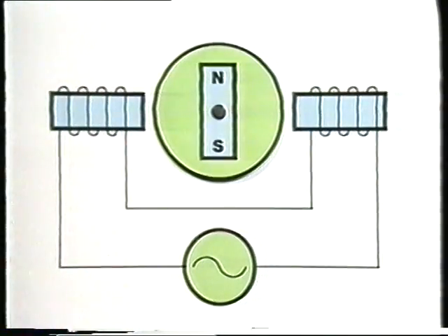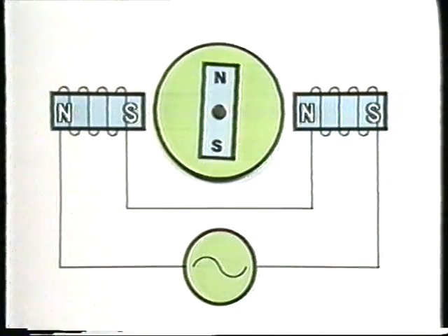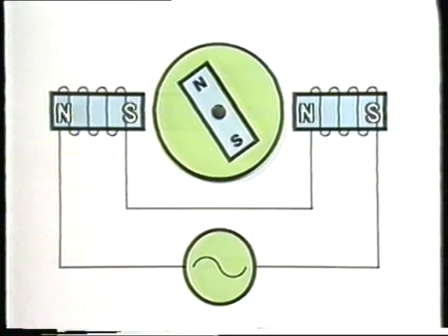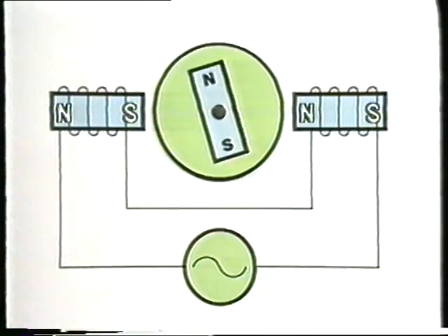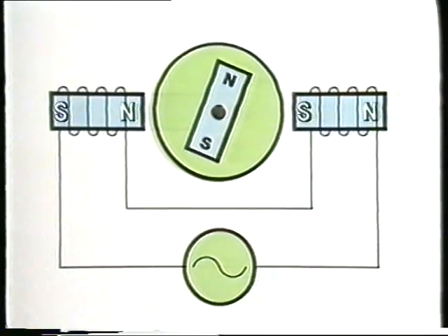The problem is that with single-phase power, the stator poles alternate back and forth but do not actually rotate around the motor in a definite direction. So at startup, the rotor poles are pulled one way and then the other as the current alternates and do not have a chance to start turning.